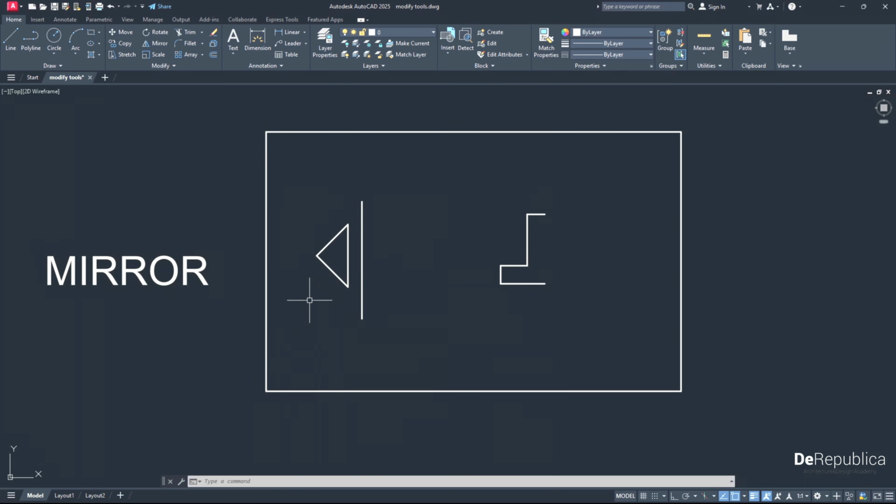As the name suggests, the mirror command allows us to mirror objects. To do so, select the object, mirror, specify the point of the mirror line, and specify the second point. Erase source object. I will show you what the difference is. If I hit yes, it will delete the source object. Ctrl Z to go back. But again, select the object, mirror, specify the first point of the mirror line, specify the second point of the mirror line. Erase source object, no. That's the difference.